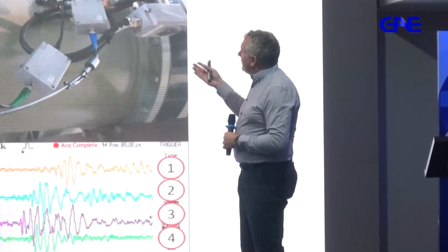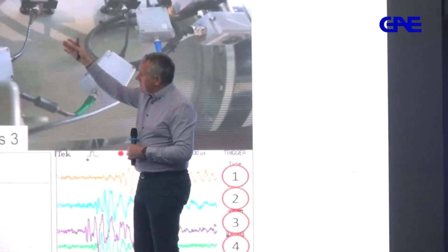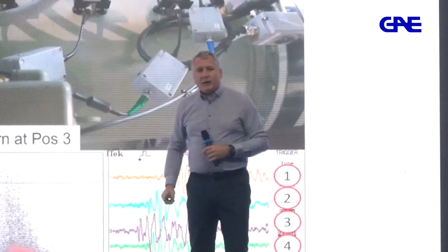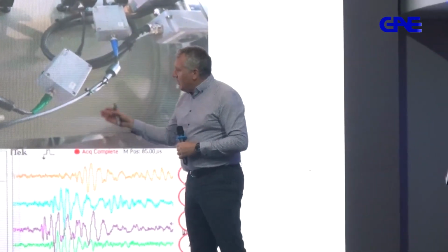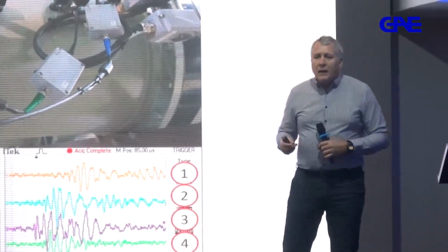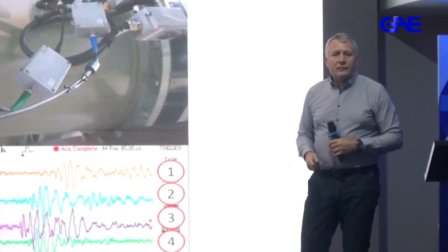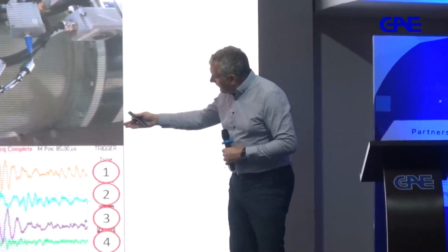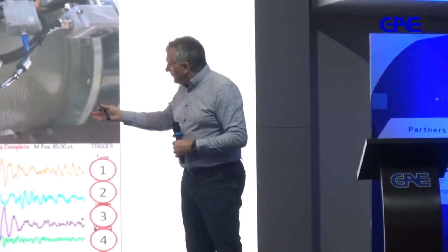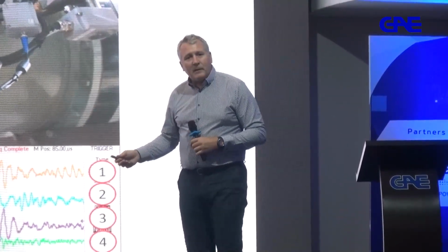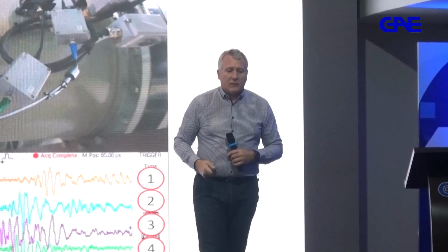So when it's applied, it looks like this. You will have, on the GIS, several such acoustic sensors, and you are going to gather eventually the PRPD diagram. Naturally, you need a synchronization signal that will help you understand where things occurred on the phase, and after that you will be able to say exactly the location of the problem. Also, you will have maybe a PRPD representation of the problem, and the net result, you're going to see in this case, is a hopping particle located in a certain area of this particular GIS.